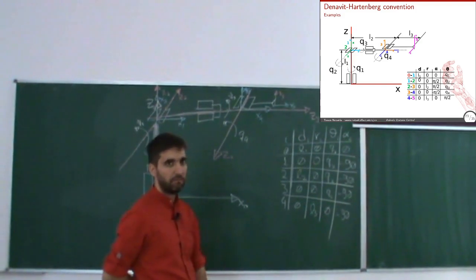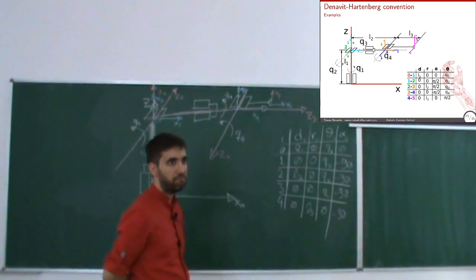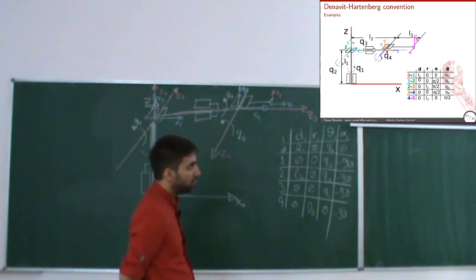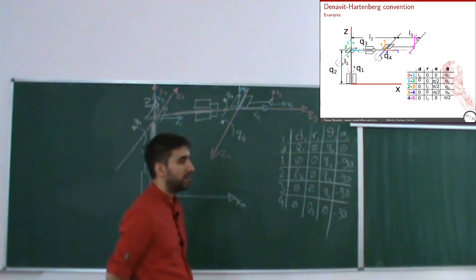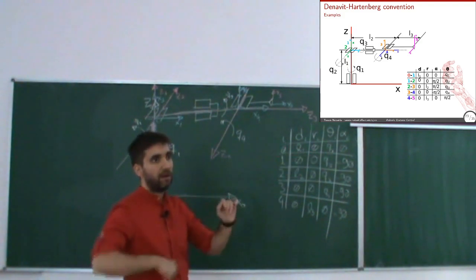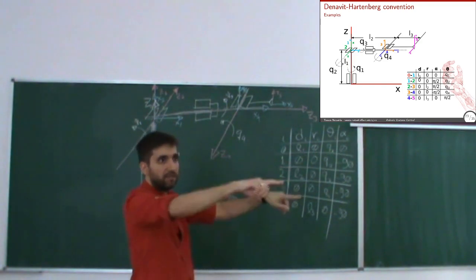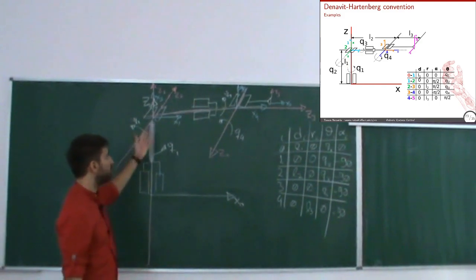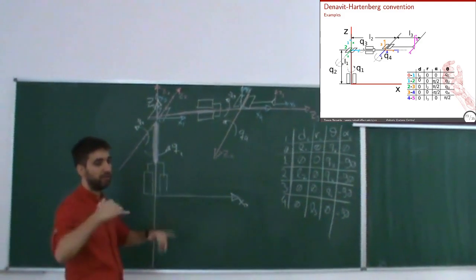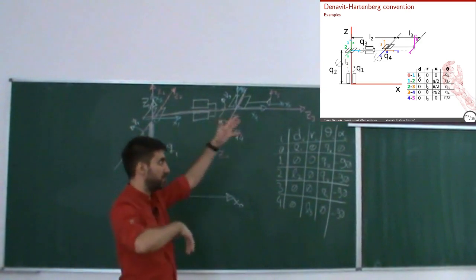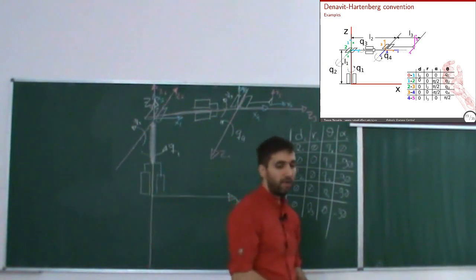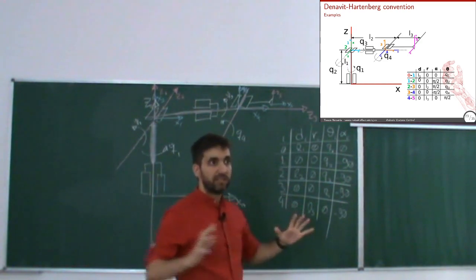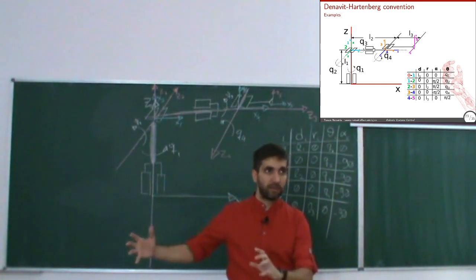How come? Basically, I can have different ways of reaching the same place. I define some axes differently, therefore some rotations are negative, while for the slides it is positive. But overall, if I use these parameters or these parameters, I should get the same direct geometric model. Otherwise, I made a mistake somewhere.